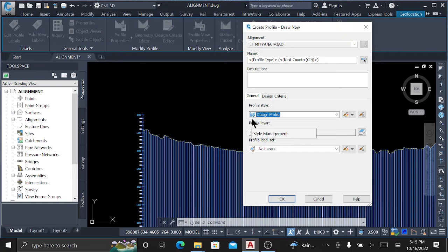For some, actually, I've faced issues whereby some of them don't actually show. By the time you try and transfer to a different point, the curve doesn't stretch as well. So I'm thinking we can probably use the filleting tool, just like we used for the horizontal alignment. So for those that the curves are not showing, please let us know so that we can help.